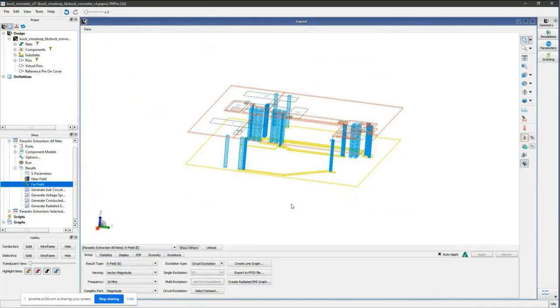But I've stretched the board out by a factor of 2 so you could start to see inside of it a little bit. And in this cockpit is where the electromagnetic analysis is performed. The layout is rigorously solved, all the metal, and this is thick metal configuration, by the way, it's 1 ounce copper top and bottom.